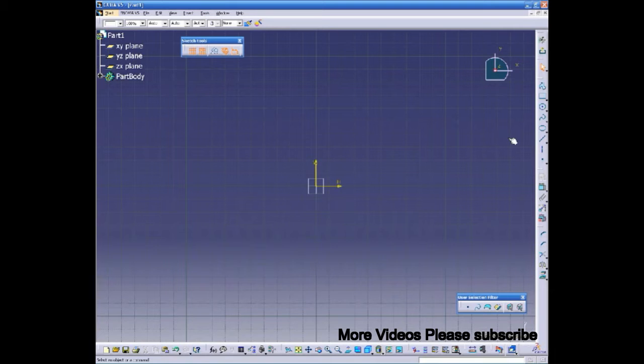First, I will start with creating absolute line. To create most of the elements, you need to define points. In this application, we have 2 ways to define them. The first way is the direct method, which means we pick the points by the mouse directly from the geometry area. The second way is to enter the point values in the Sketch Tools toolbar. OK then. For now, let's use the direct method.